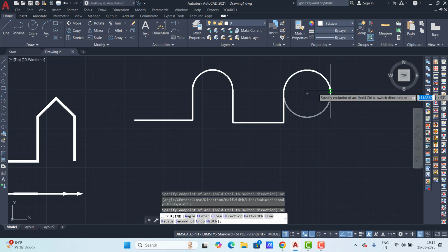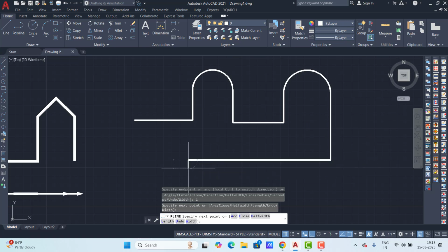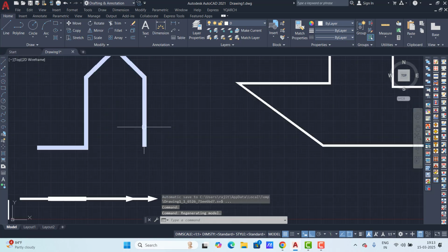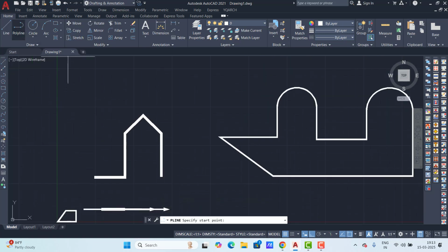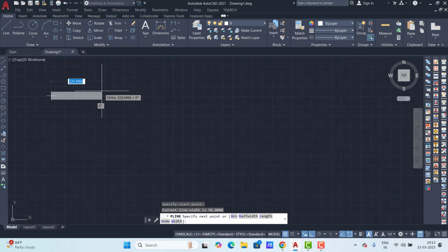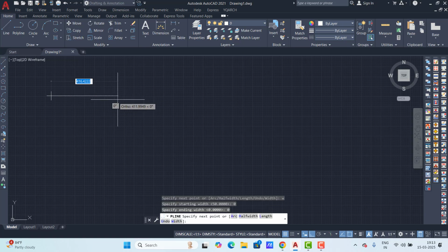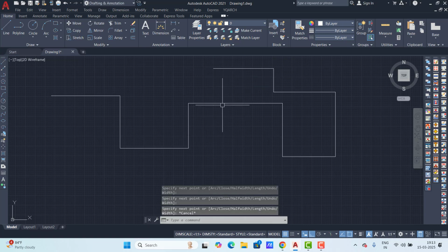Okay. Now, understand polyline edit. So here is a polyline, and inside it is the edit polyline option. The shortcut is PE, enter. Suppose you have made this line and you want to convert it to a polyline. When I select this line, you see thickness is not coming, only length is showing. I want to apply a thickness.